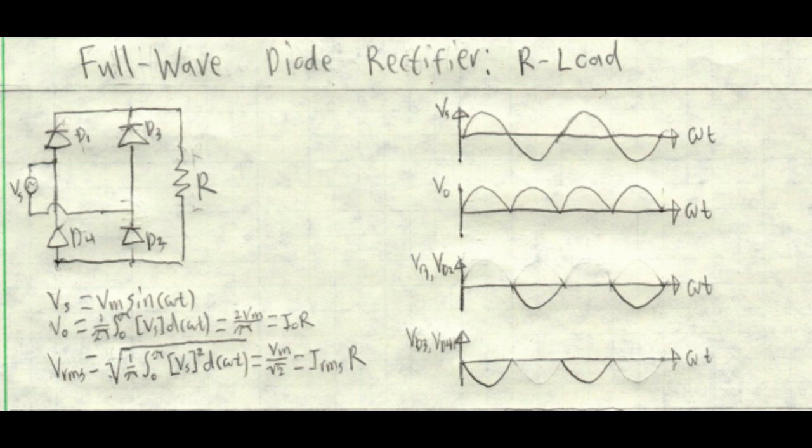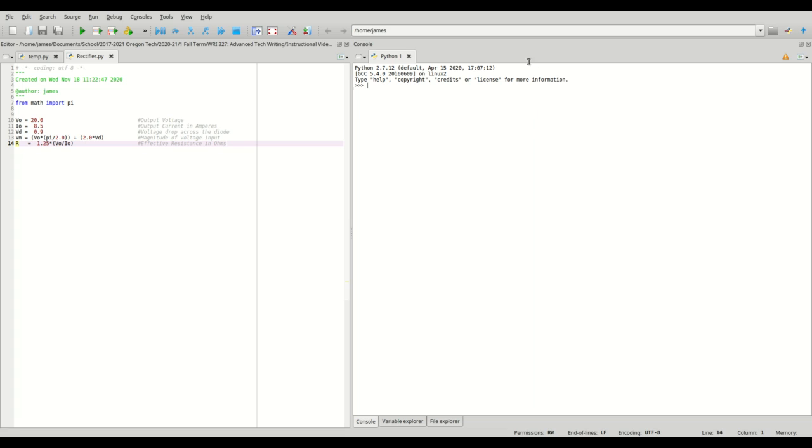In this tutorial, you will learn how a bridge rectifier works, and how to design one in LTspice. To keep things simple, we will be modeling a resistive load. No inductive loads, no freewheeling diodes. Keeps things relatively simple. According to the specs on my charger, the average DC voltage output is 20 volts, and the maximum current is 8.5 amps.